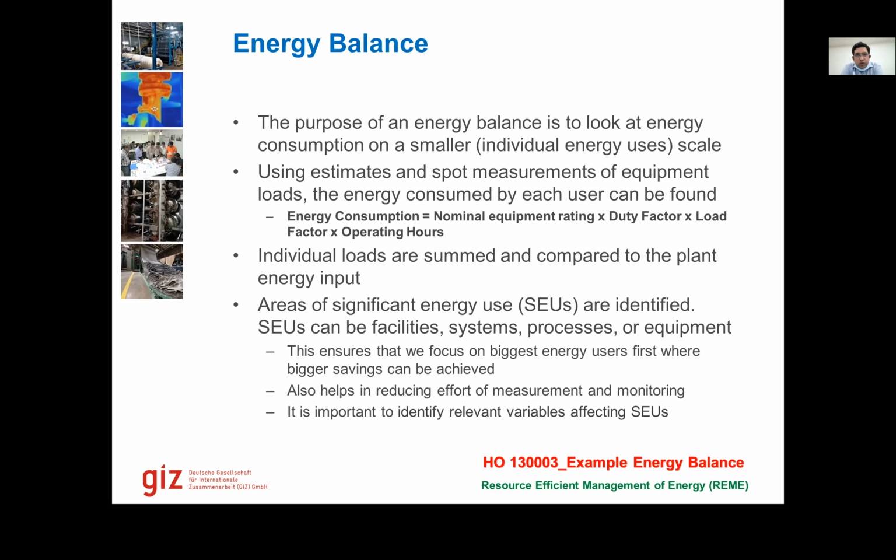Then we also need to see if this machine runs 24 hours every day, or does it also have stoppages like changeovers or maintenance. So we estimate that duty factor as well. And then how many overall hours of operation do we have in a year? We multiply those together and we can estimate energy consumption.